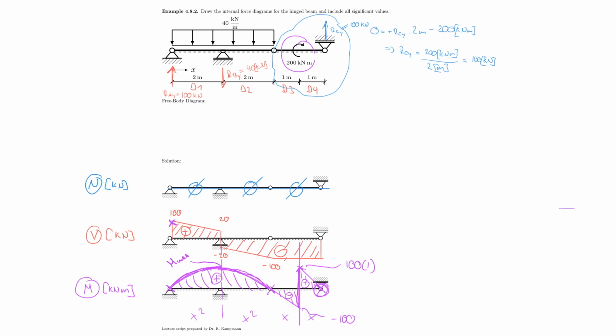And so you see, once again, the moment diagram is no different than before, except that your moment has to pass through 0, of course, where your hinge is situated, and nothing else goes through 0. In this problem, we also added this nice little feature of the concentrated moment to make us aware of the fact that the concentrated moment has an effect on the moment diagram, but nothing on the shear force diagram. And I think this concludes the problem, and we solved it completely.